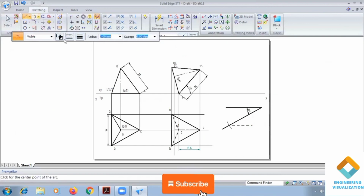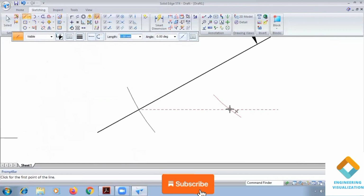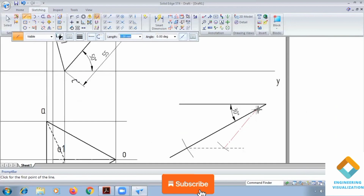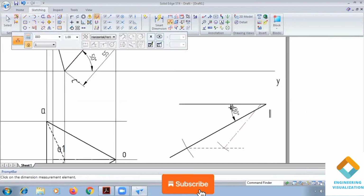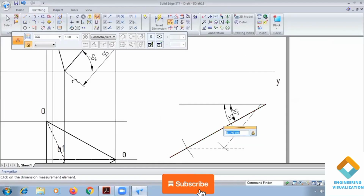So cut the second arc using arc by center. Just move the cursor on the first arc and you will get the reference point. Now type the radius 35.16, press enter and cut the arc. Now join this second point which I have cut. Yes, zoom in and get the point. Just extend this line using the extend to next command and find out the beta angle. It is 51°. So we are getting the exact angle here, guys.